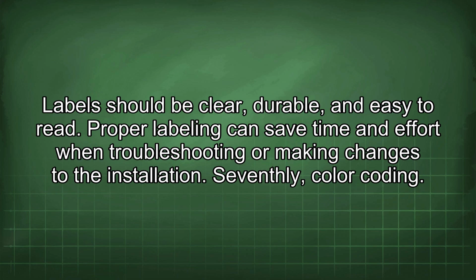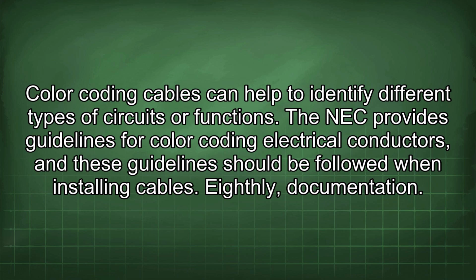Seventhly, color coding. Color coding cables can help to identify different types of circuits or functions. The NEC provides guidelines for color coding electrical conductors, and these guidelines should be followed when installing cables.